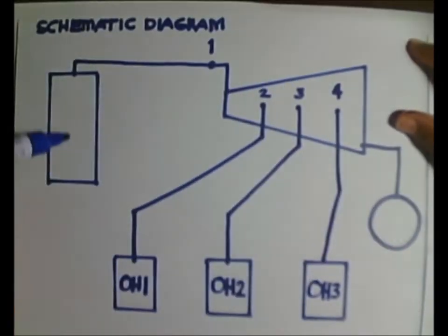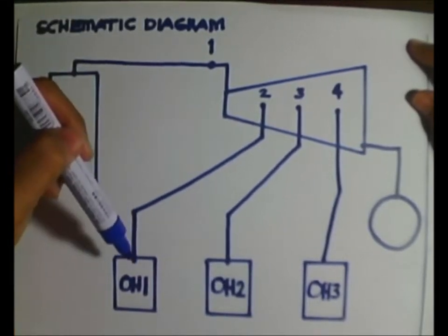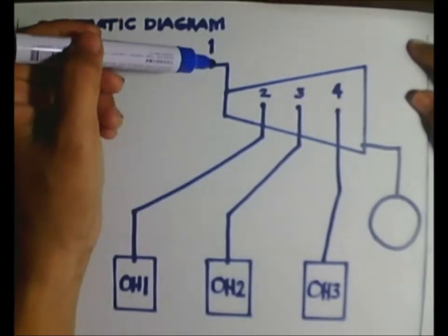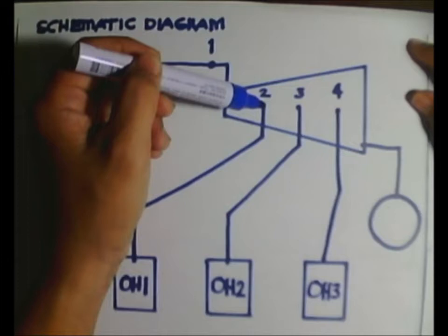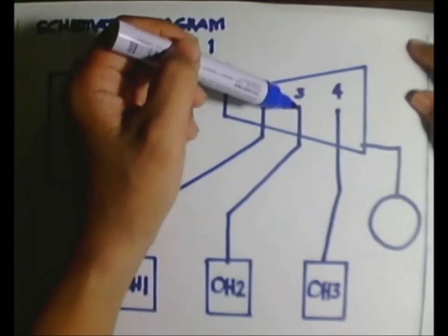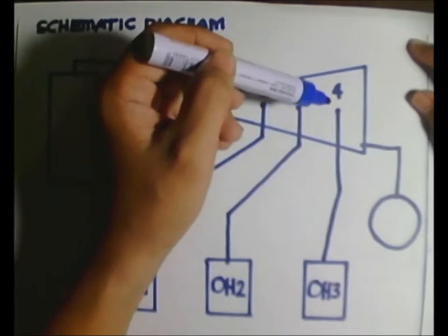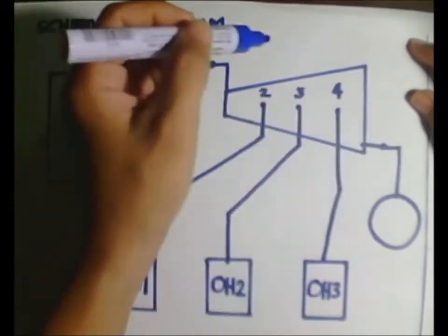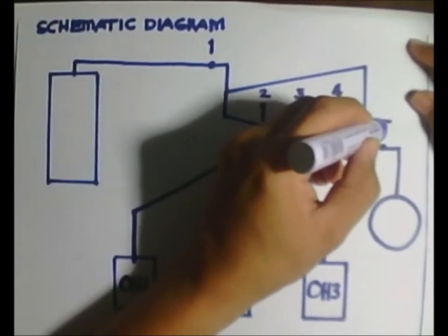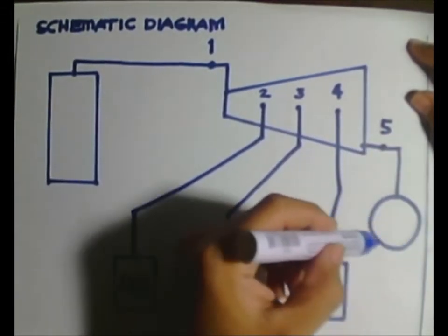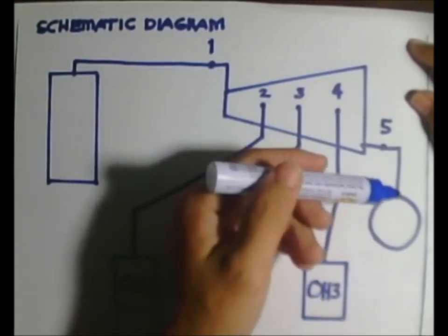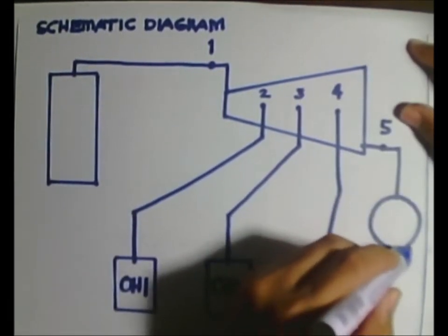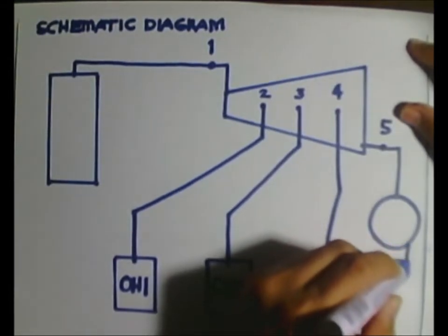In this example, we have 3 open heaters in effect to this cycle. So we have from 1 to point 2 an extraction, and another extraction at point 3, and another extraction at point 4. Now finally, steam comes out from our turbine at point 5. It then enters into your condenser, and there is a constant pressure heat rejection process that takes place here, so that steam becomes saturated liquid,